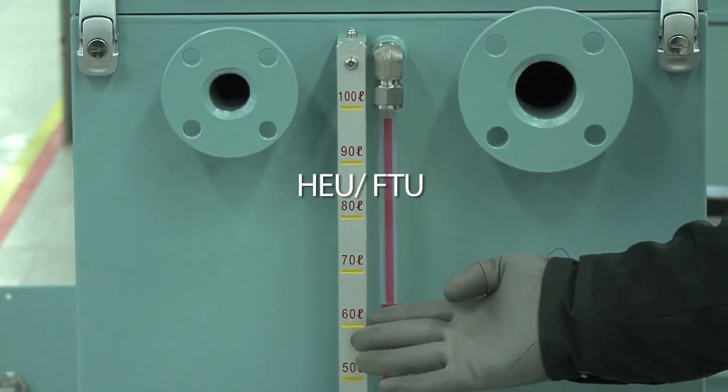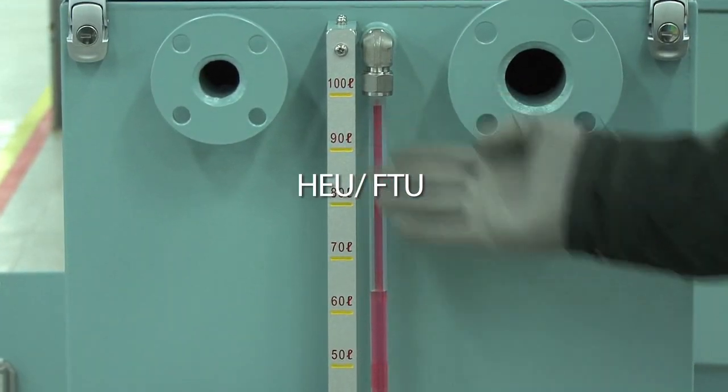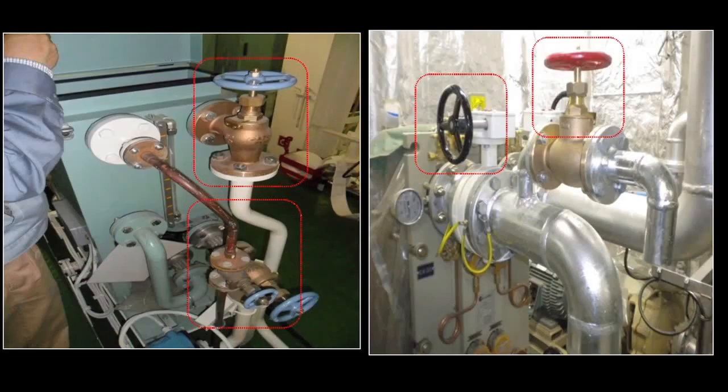8. HEU, FTU, optional. 1. Fill the level of cooling water more than medium level of FTU. 2. Open FTU inlet and outlet valve of fresh water. 3. Open HEU inlet and outlet valve of fresh water.